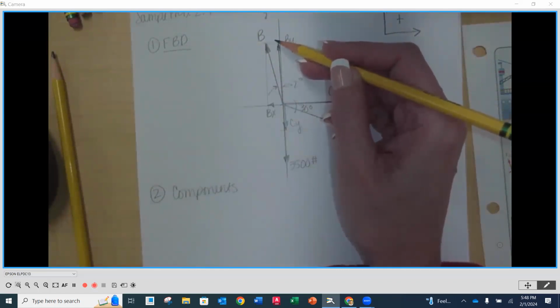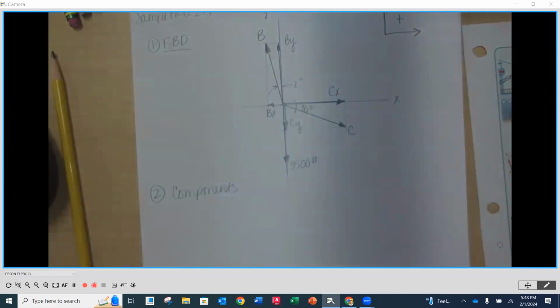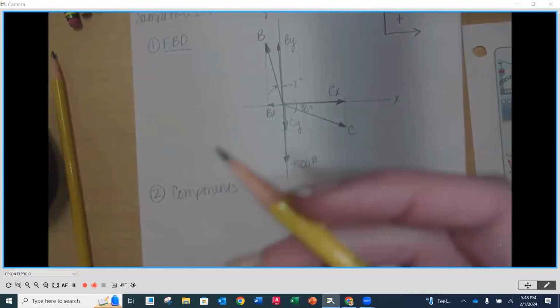Again, do not put your X component labeled up on the top here. We need it at the place of application. That's really critical. You might not think it is, but it is. Because later on, when we have forces that are going to be along a line, I've got to know where the X component is. I got to know it, all right? Because it's going to cause rotations and they're not floating away from the body.